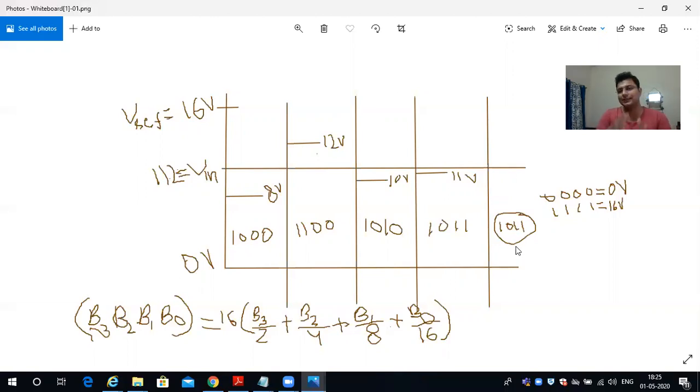So in this way successive approximation algorithm functions. If it would be 12-bit, then instead of 4 it would be the 12-bit approximation, and then the algorithm would be much more refined. The digital output would be much more refined. So this is all about the functioning of successive approximation algorithm. Our LPC module uses 12-bit successive approximation algorithm.